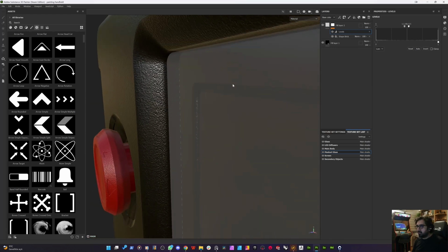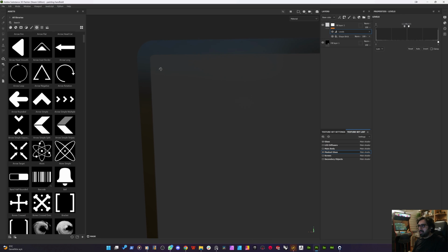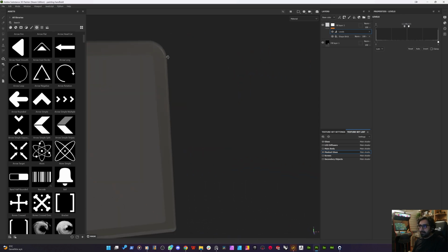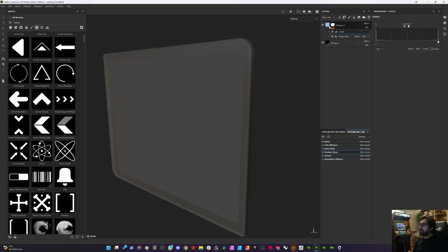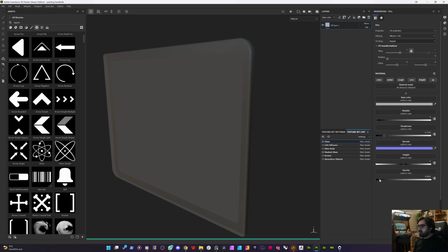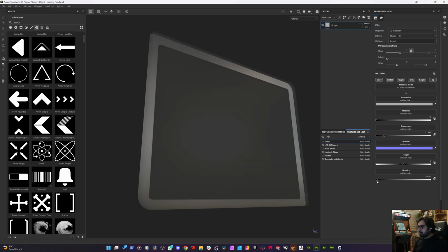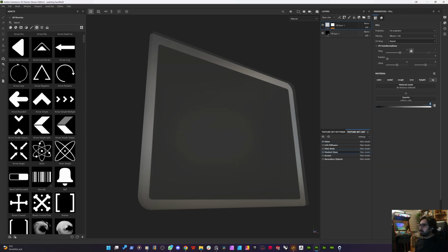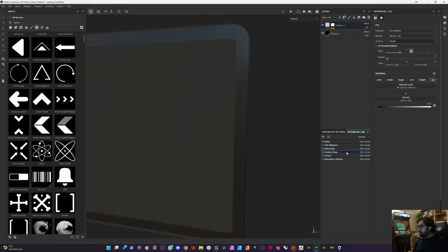What I do here is setting a mask for the back side of the mask glass. Let me show you. This is the masked area that I created. So this part will be fully black, but inside will be transparent, like the glass on the front part. And this way I will set the opacity, let's make it 0, and for the glass I will set the opacity as 0 as well. Let me see if we can get any reflection. No. So I'm setting it as 0.02. I will do the same for the mask glass, like this. So we will be having a glass that has been masked from the back surface.